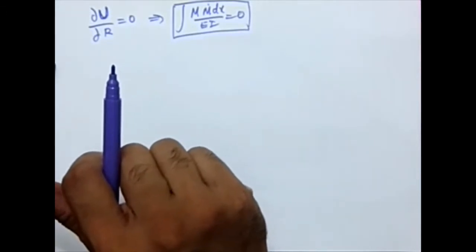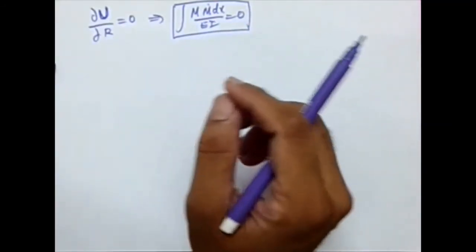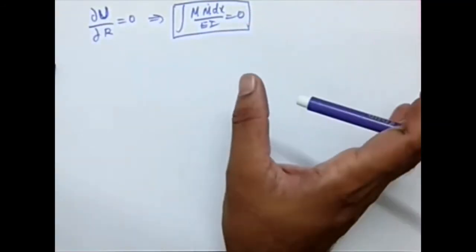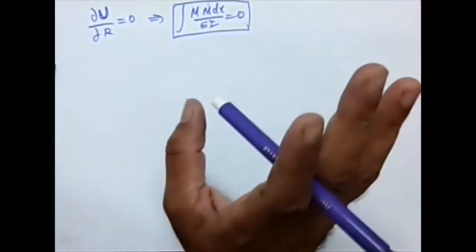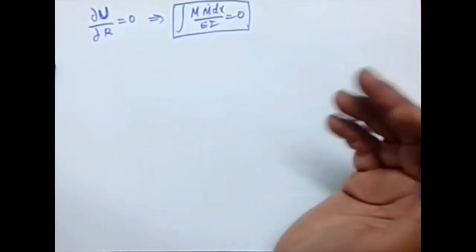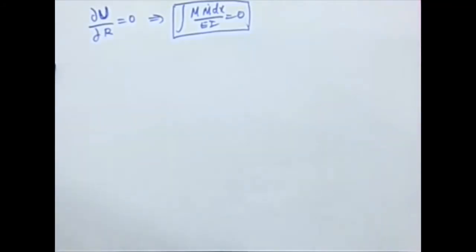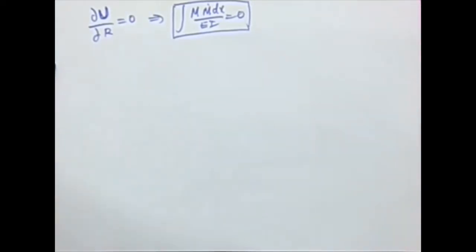What we dealt with was the case of a propped cantilever, which means we have a fixed support at one end and a prop or a roller provided at the opposite end. So that's the case of a propped cantilever. Now we are going to talk about another major and common indeterminate structure, the continuous beam. So we'll directly jump into a problem.